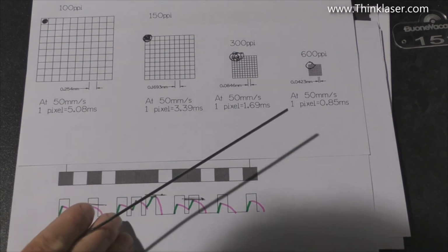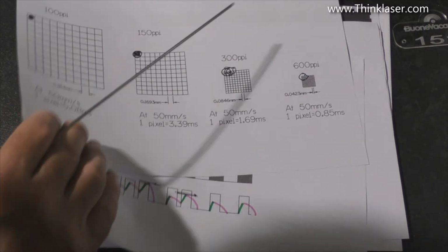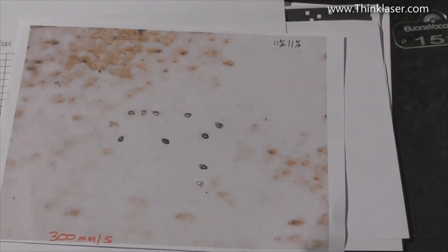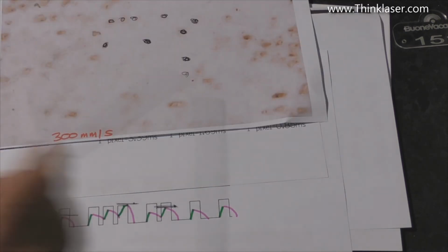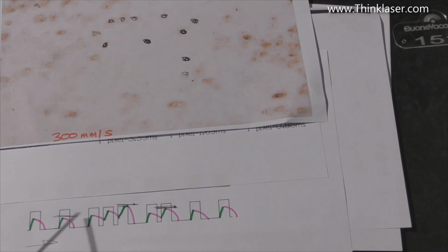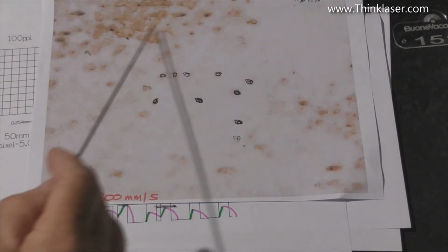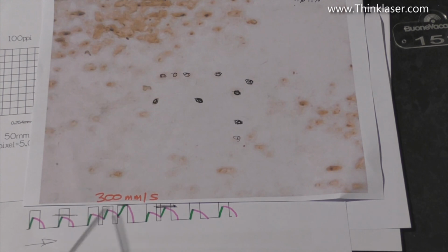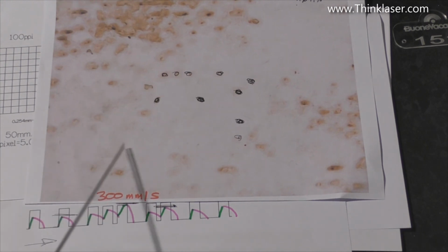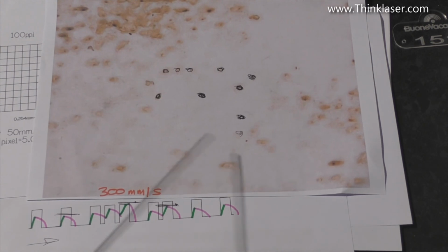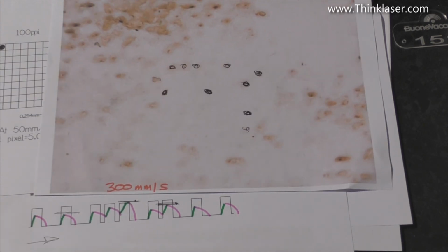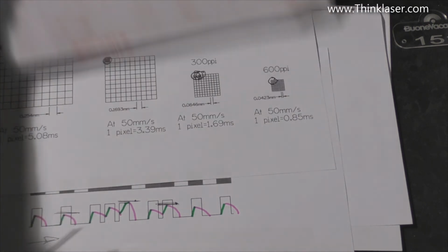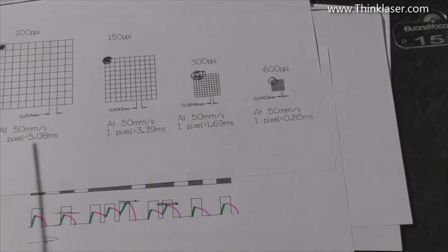And remember earlier I was saying to you, I was trying to find an explanation why our dots were not all dark black. Well, here we are. We've got different groups of dots here which operate at different powers. Where we've got groups of 3, 4 and 5 dots up here, we've got a dark burn. But where we've only got single dots, we've got hardly any burn at all. And then we may have double dots and triple dots. That isn't what I was expecting, but that's what we're going to get if we drive the resolution too high and if we run the speed too high.